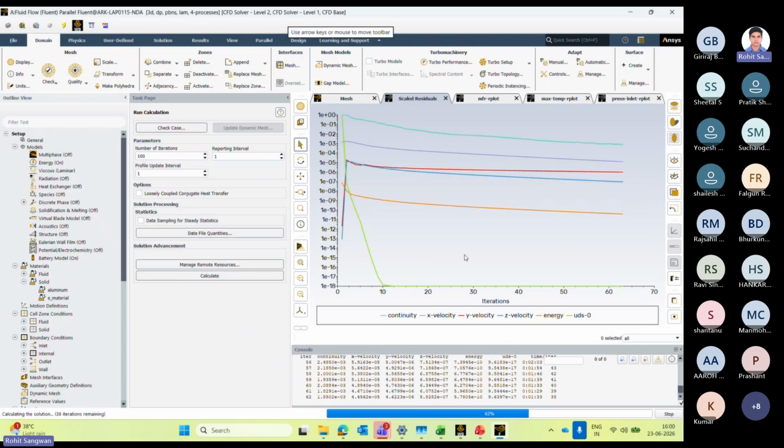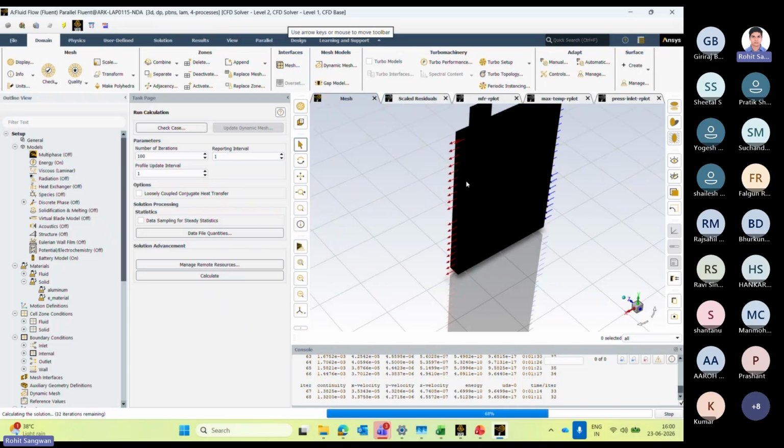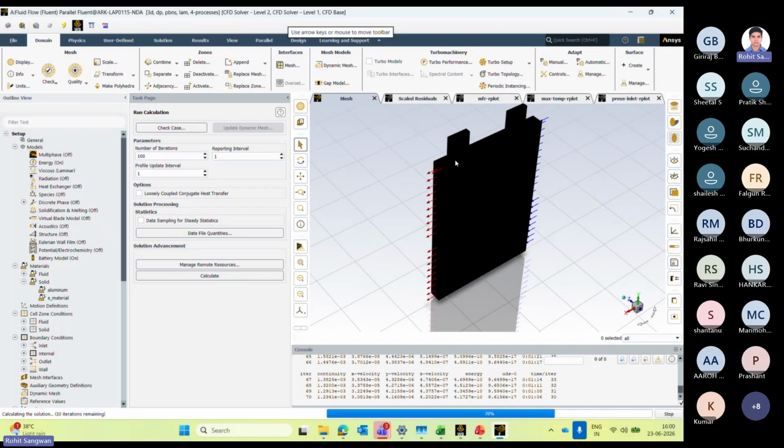In this case, even if we turn off the energy flow equation, you will see the temperature of the battery will also be very low. The main reason is that even if we are not flowing the coolant, the heat will pass through this surface area. We have added more surface area to take away the heat from the batteries. So sometimes it depends on the battery, and the thickness and dimension of this cooling system also play a very important role. Sometimes we might have some blockage or we might close it.